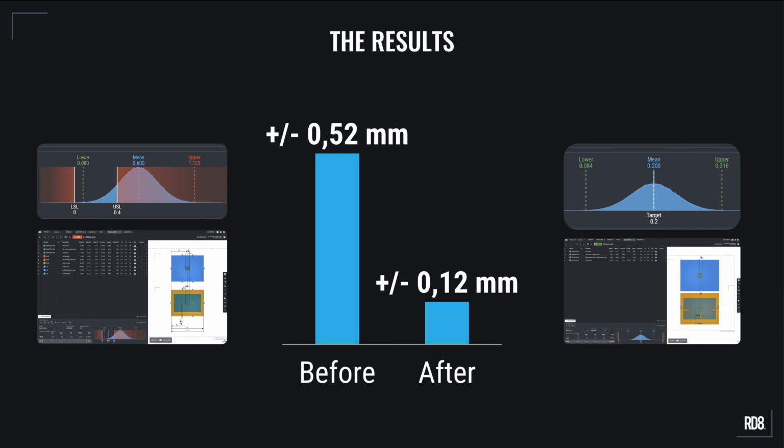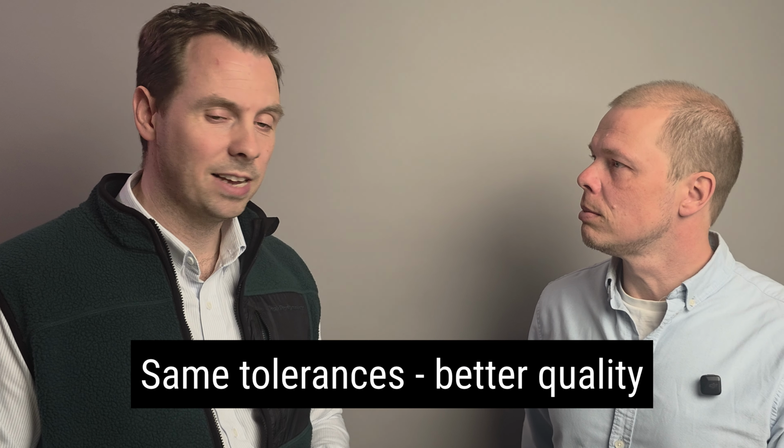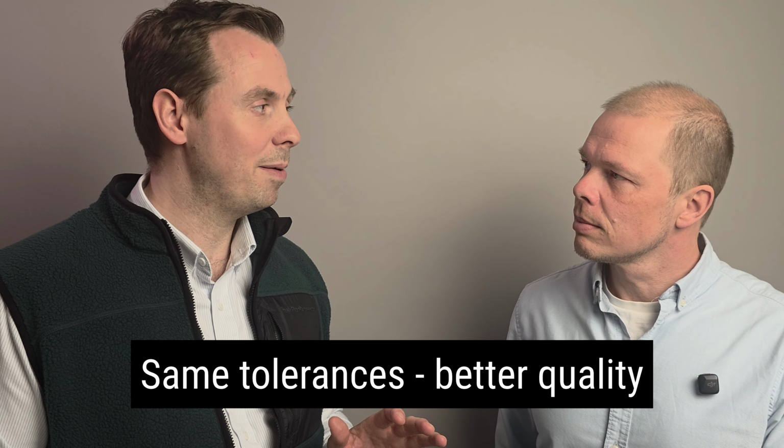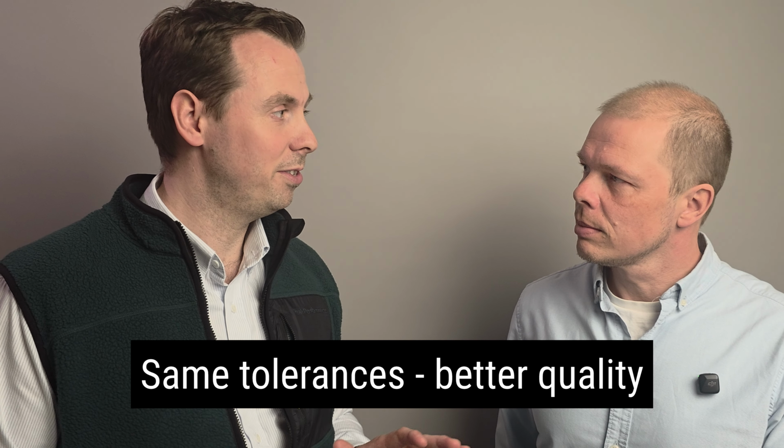Mm-hmm. So if we take a look at the results in the initial non-optimized design, we have a window of variation of around plus minus 0.5. And in the optimized scenario, we have a much better performance. There's a variation of around plus minus 0.12. And you pulled this off by optimizing the design so that the tolerance capability level, the tolerance grades and classes, are the same as before. Exactly. No changes to production requirements at all. The same assumptions applied before and after.